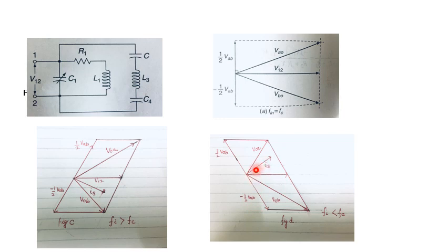Hence, the voltage across the upper diode is decreased, and the voltage across the lower diode is increased. So we can easily make out that in the output load resistors, the voltage across R3 is smaller and the voltage across R4 is greater.